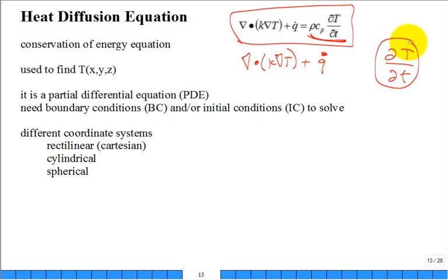It could be accumulating internal energy, and it would be represented by a higher temperature going up with time. So this is an accumulation depletion term. Okay, it basically is a conservation of energy. Not all forms of energy, but just a particular form of energy, the internal energy. Internal energy transfer by conduction, showing up in the energy equation by the electrical resistive heating and other things, and then the accumulation of internal energy.